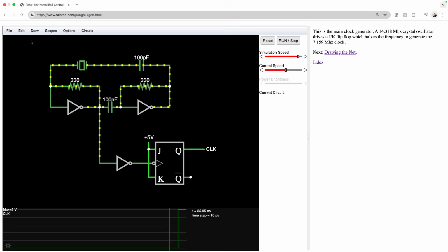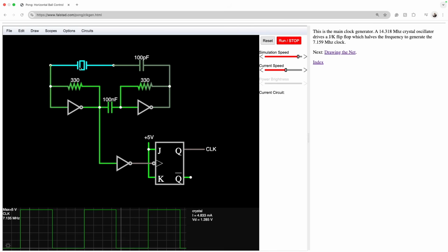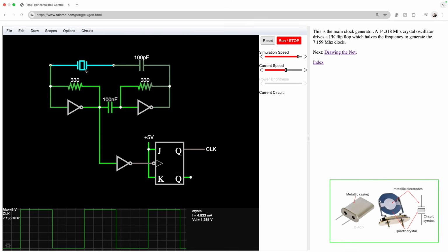And for that, if you look at the clock generator, look at this one right here. This is the symbol that I just showed you, right? So we're going to have, let me just stop. We have this circuit right here, which is responsible for using a crystal oscillator component, right? One of those crystals that you can buy. And when you buy this component, it is that metal shell where inside you have a very small slice of quartz crystal with an electrode to which you actually apply electricity, and that little slice of quartz crystal was sliced precisely to give you a certain vibration.